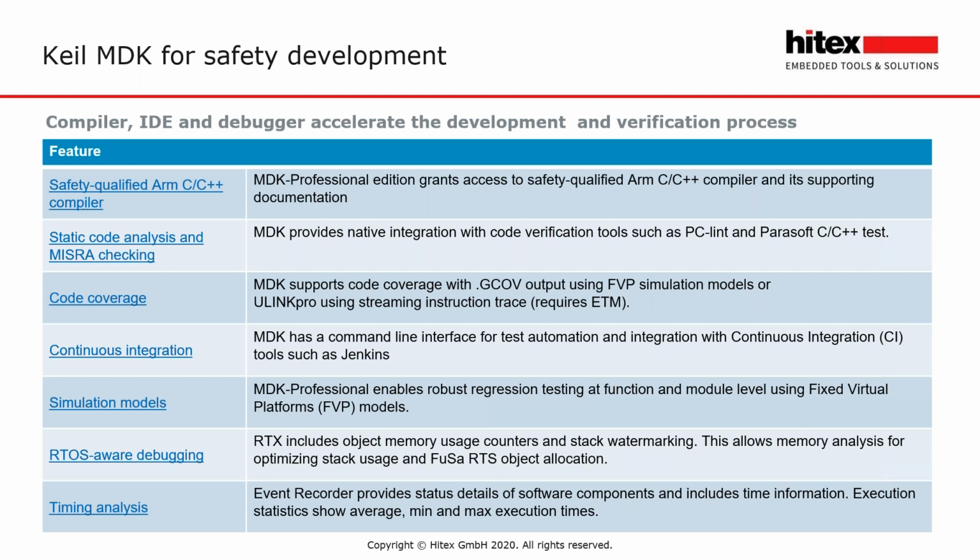The MDK is also available with various simulation models. These basically allow you to run your code on a simulation of the Cortex processor. Depending how you've structured your code, that can be quite useful for software testing and also analyzing bits of the C code that are isolated from the microcontroller peripherals. So again, simulation models have a very good role to play in testing and validating code.